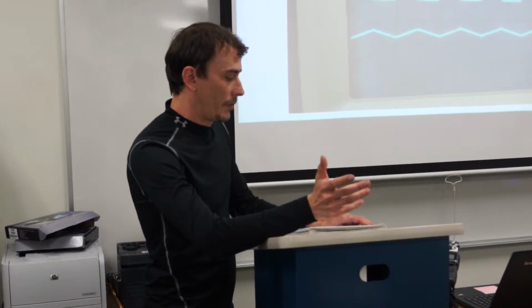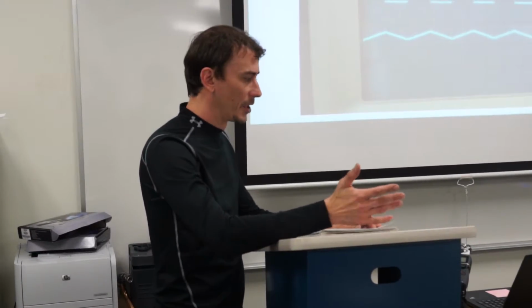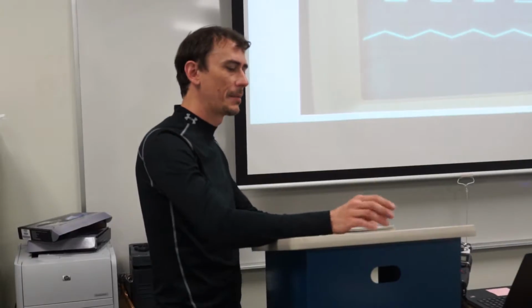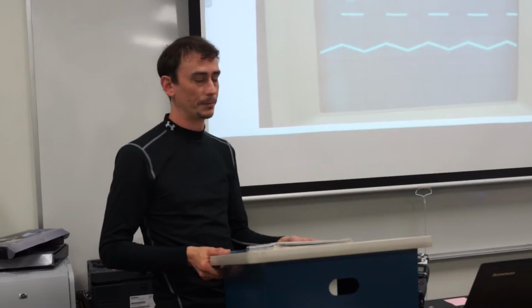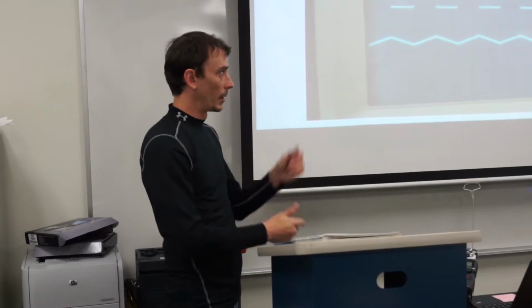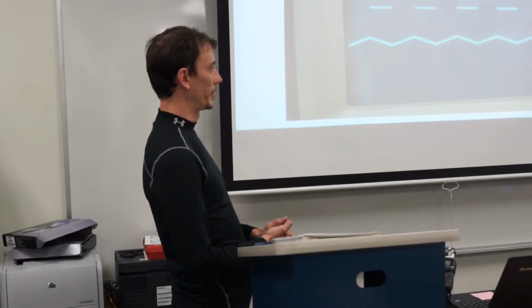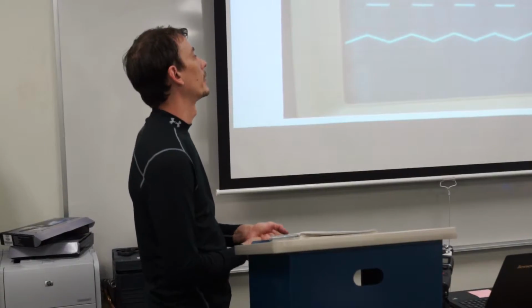And the 8 bits of control, 19 millivolts, might seem a bit extreme in step size. Like, why do we need that fine of control? Well, this is our raw output's 5 volts here. That output can be taken and amplified to run all kinds of motors or arrays of light systems or whatever. So once it's amplified, now the resolution might actually be useful. When you're controlling a broader range, it's good just to have the control there. So that benefit would be realized after some form of amplification past our 5 volts.